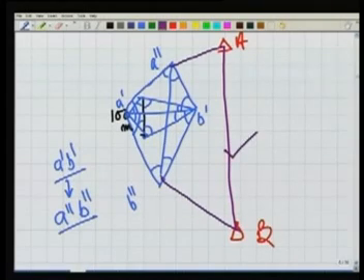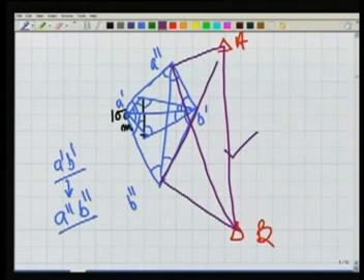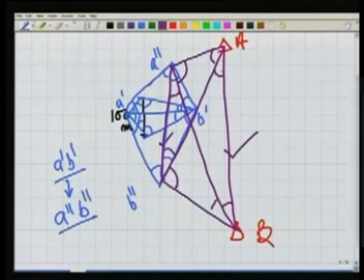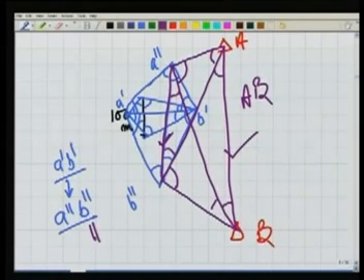My purpose is to determine this length. So what I am doing, I know this length A double dash B double dash, as well as I measure all these internal angles here. I can occupy AB and we can measure these angles. So once we are measuring these angles using the figure here, starting from here and the internal angles, I can compute the length of AB. So from A double dash B double dash we have the length AB.